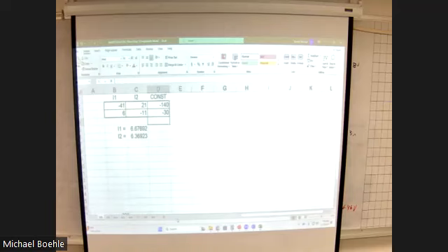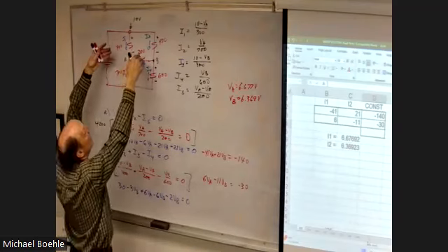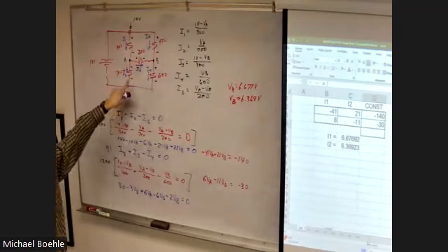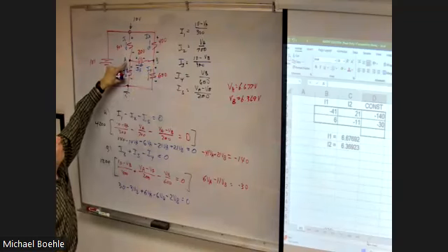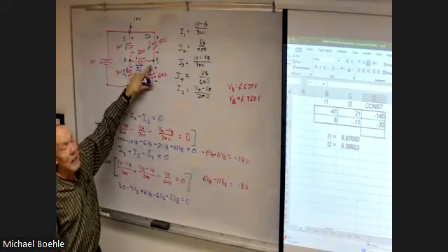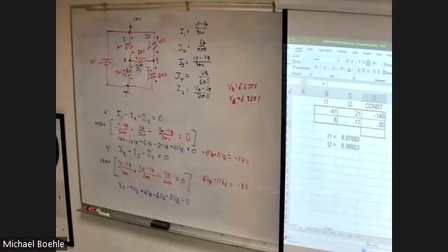All right. So now, for your lab, what you're going to do is you're actually looking for the voltages across all the resistors. So the voltage across this resistor would be voltage A minus voltage B. The voltage across this resistor is voltage A, voltage B, 10 minus A, 10 minus B. There's your voltages. Or you just take those voltages, plug them in with circuits and get currents, right? Because I asked for both the voltage and the current. That's the easy way to do it.